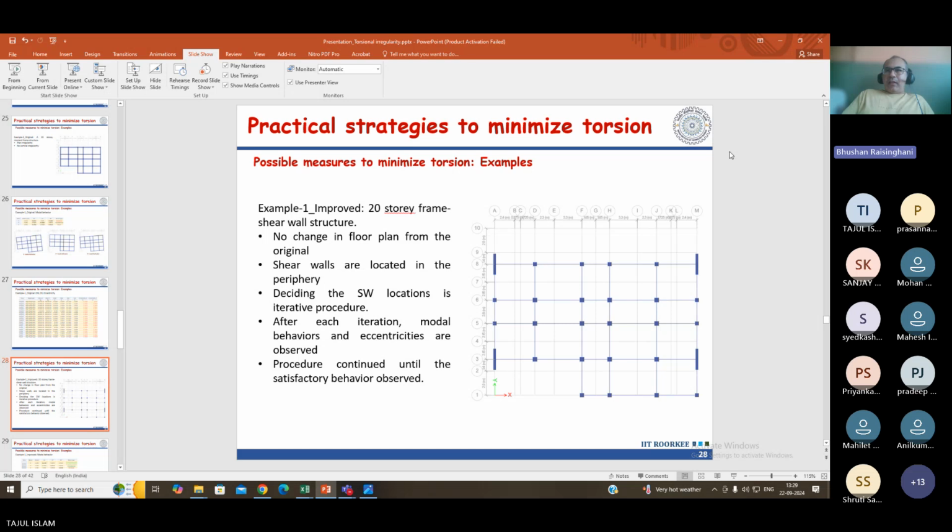So that needs to be checked, because design for twist in the column, I don't think it is directly considered, but the only way is to take it as equivalent shear. No, it will not convert to equivalent moment. It will not convert, because in the beam, if you observe, the software will take moment and torsion. When you give the design command in the beam design, it will convert to equivalent bending moment and equivalent shear. It will convert while designing, but in the analysis, it will not convert.